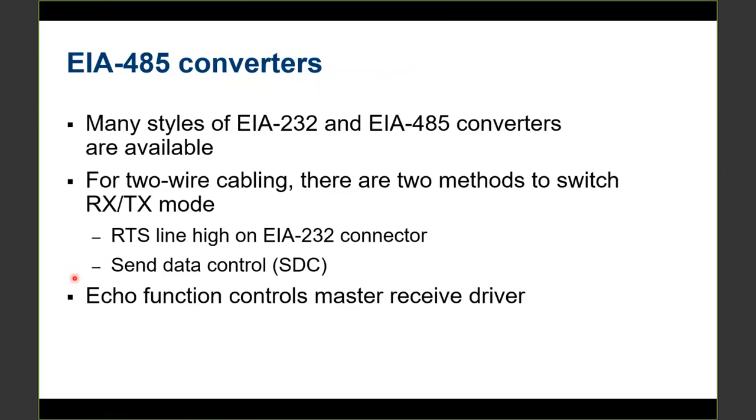One mode is you can use the RTS lines, basically using your hardware flow control to turn on and off your transmitter and receiver. If you use this method, you select it on your 2886 with dip switches, or if you're using a third-party converter, this RTS line basically means you're using the RTS CTS handshaking to control your transmitter and receivers.